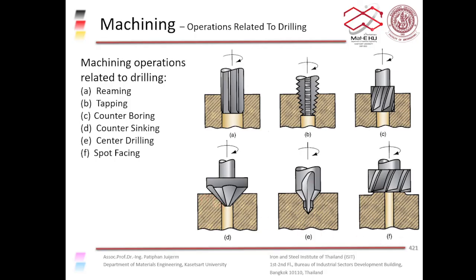Center drilling, or centering. Basically, this process is to drill a starting hole, right? To drill a starting hole to establish a good location for subsequent drilling.